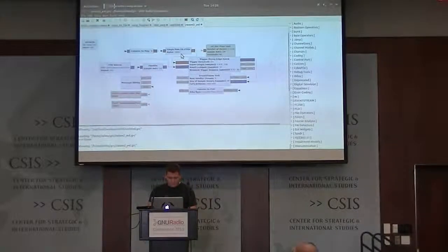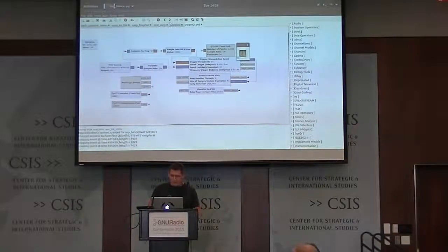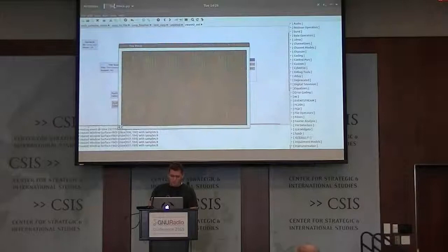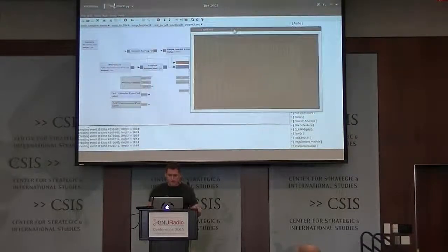So if we send these to a message-based complex time plot, we should be able to look at the samples for each of these events. So here now, every time we pass this threshold, we're extracting these 1,000 samples, we're throwing them over this message plotter, and we're plotting them. So this is basically doing kind of the same thing as that stream trigger was, but now we have them in messages. So if we want to do some kind of a message operation on them, we can do that. So you've got kind of the same tools here.